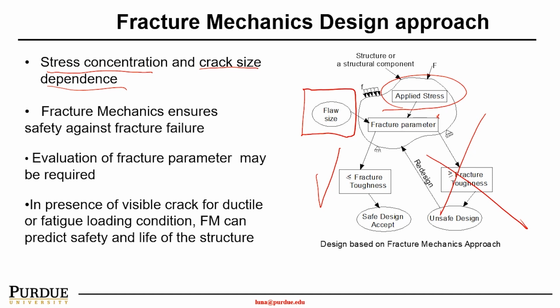So therefore, we want to use non-destructive testing, particularly when the material or structure is still within its service life, to understand the crack or flaw size. And as long as this size is smaller than the threshold, we're still safe. So the structure can still be in service.